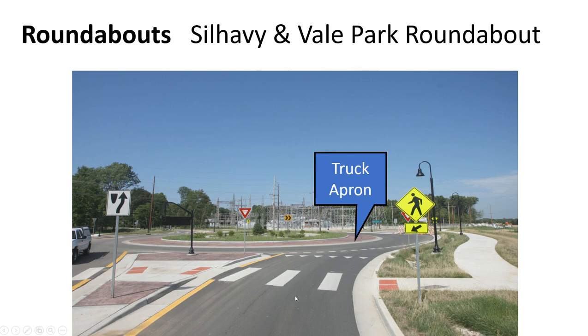And you can see, as a car, I'm not going to want to go up on that curb, even though it's a sloped curb and it's only 4 inches tall. And then we often put patterns in here. So this is often brick patterns, and it makes a rumble sound or vibration in the car. So people don't like driving up on there. They don't have to. Truck drivers don't notice it because it's on the trailer tires. Up there, they don't feel the rumble very much at all. But as a passenger car driver, you're not going to want to be up here. And that's the whole point. We want to keep you off of that.